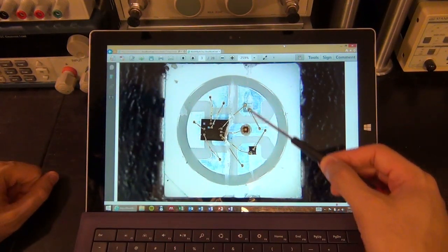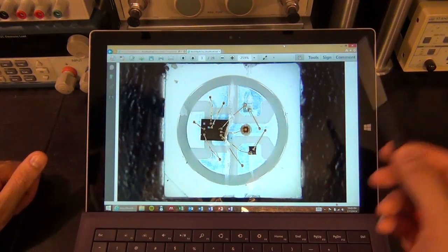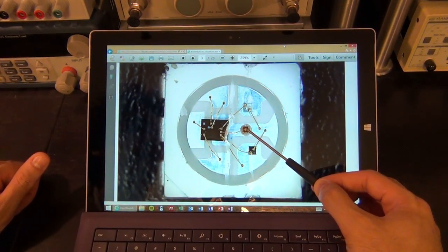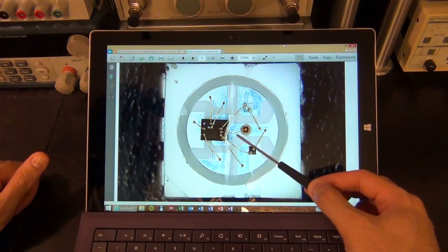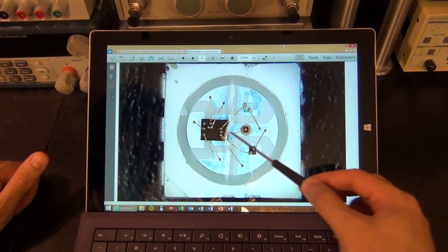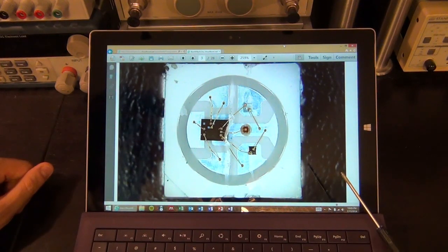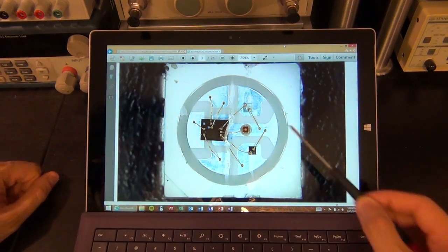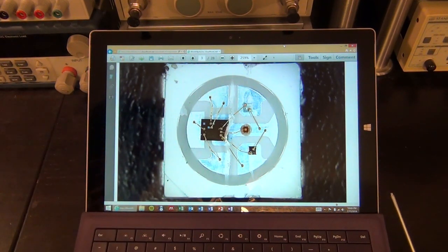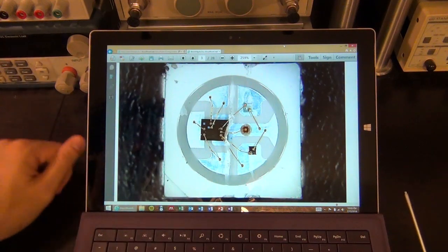Now, this is what's inside any LED. If you pick up a red LED, you will only see one of these, where there's a wire bond connection to the top surface, and the bottom surface of the PN junction is connected to this trace at the back, and that's how positive and negative is applied to the PN junction. Remember that the different colors from the LEDs have to do with the dopants used inside the semiconductor, and I've talked about that in a different video that I've made.